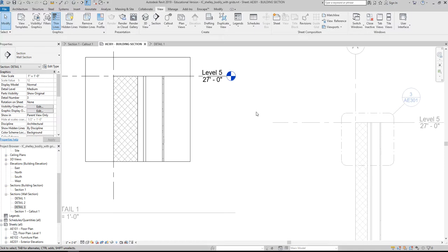The footprint has been placed there, and what we would do as we finish up our drawings is we would add what are called detail components, right? So we would add the insulation, we'd add the notes, we'd add the dimensions, we'd add the studs, we'd add all of that detail in there to convey for build, right?